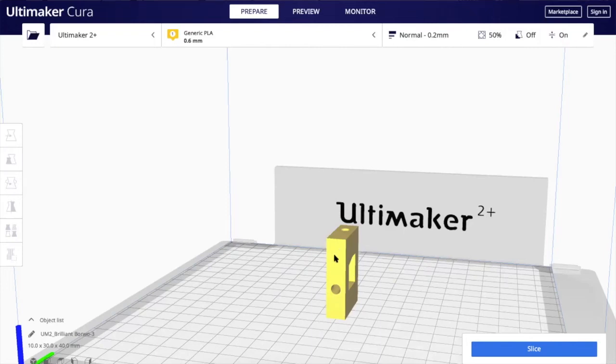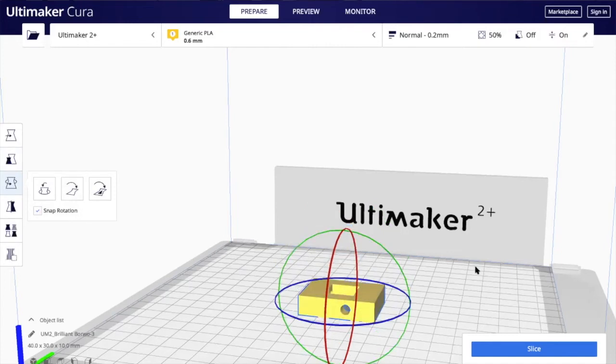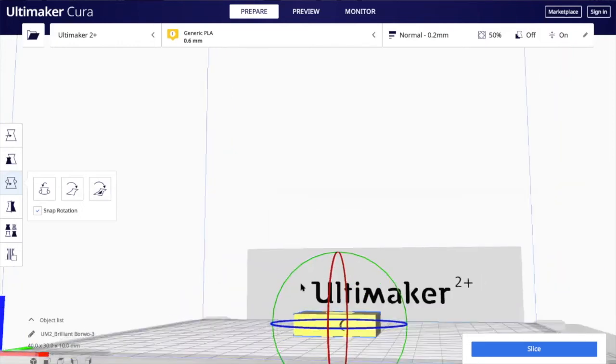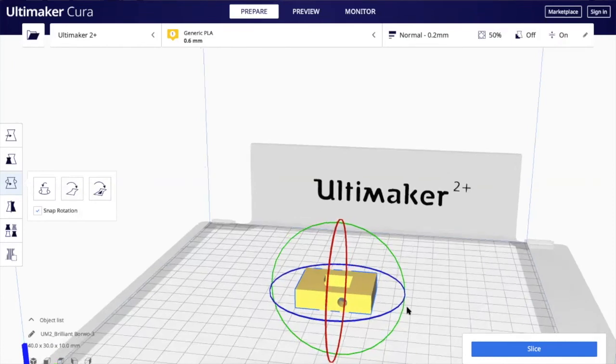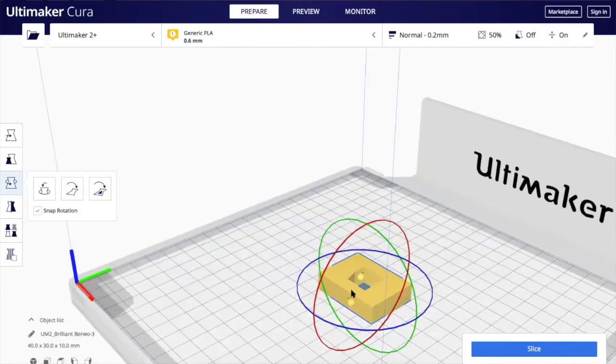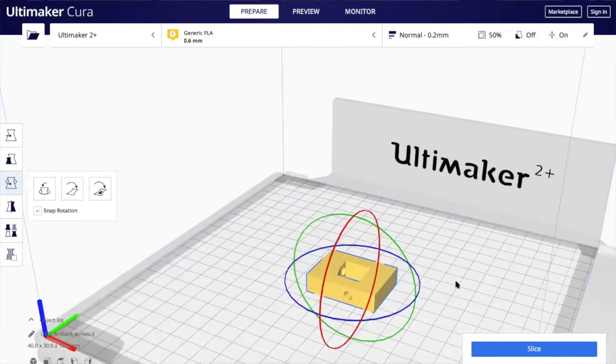So it will be stable, but not so stable if you try to bend it in those directions, because you can just simply break those points. If you want to have stable in that direction, it's better to print it in this version. So the layers are in this direction. Now, if you try to bend it, it will take way more force than if you print it in the other direction. That always depends on how the layers are printed.